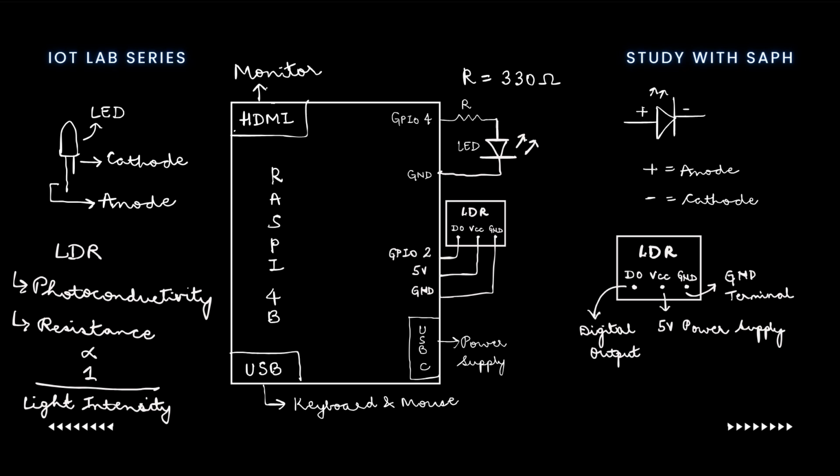Whenever this happens, it indicates that the state of the LDR is in a way true. And when the GPIO pin becomes true, we are going to be writing a logic such that we'll be turning on the LED anytime it is dark, and this darkness is detected by the low light intensity values detected by the LDR sensor.